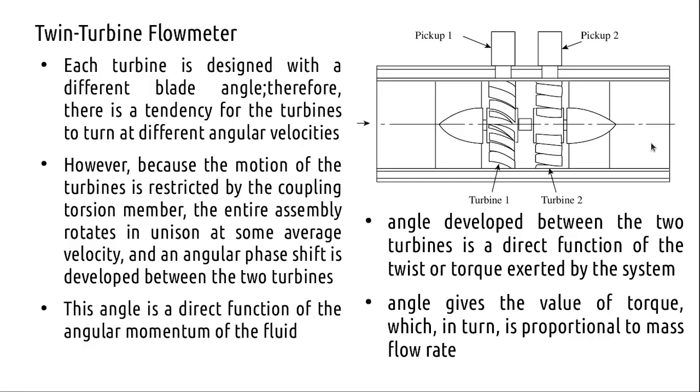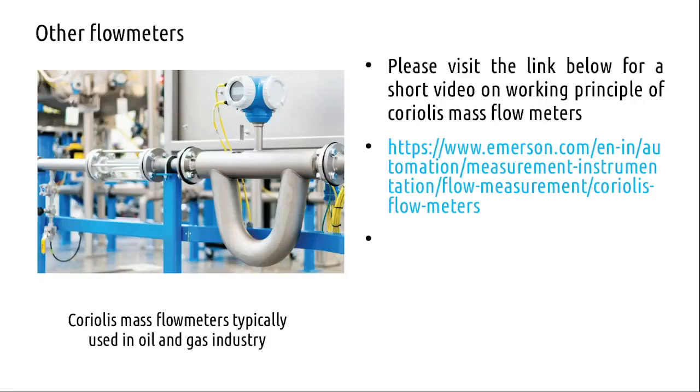And finally, what happens? The angular phase shift will be a function of the angular momentum of the fluid, and that will be proportional to the mass flow rate. So that is the summary of whatever topics are there in the third module.